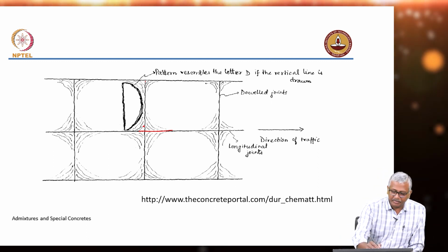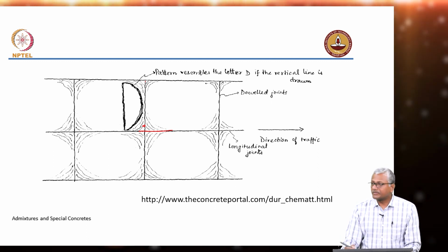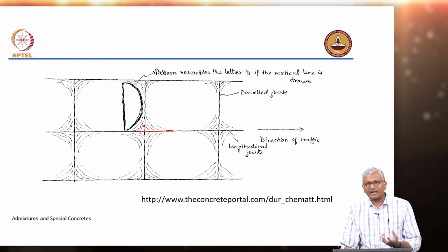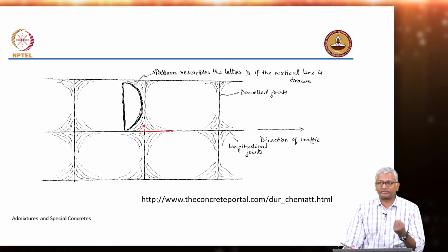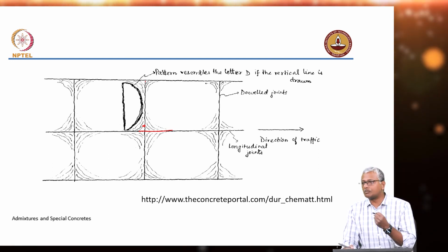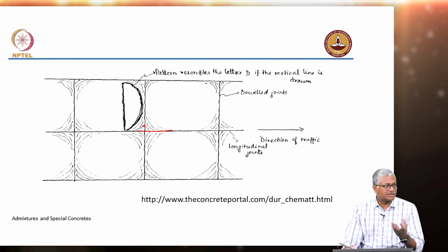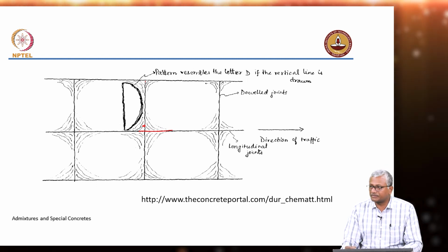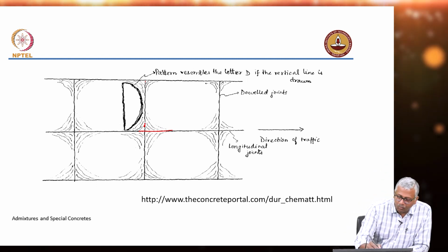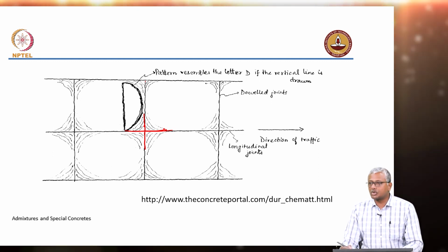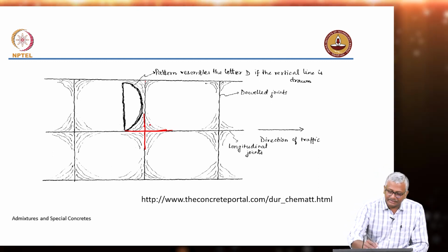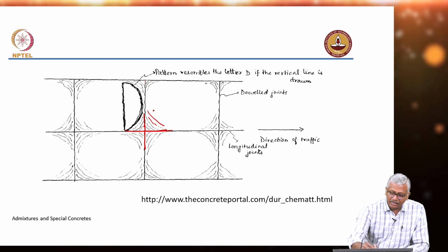So, water basically penetrates the joints, and if there are aggregates that are moderately porous inside, they will absorb that moisture, and that moisture transforms to ice during freezing cycles, and that leads to cracking of the paste. So, essentially water concentration is going to be quite high at that joint, and because of that the cracks start appearing almost in a parallel fashion.